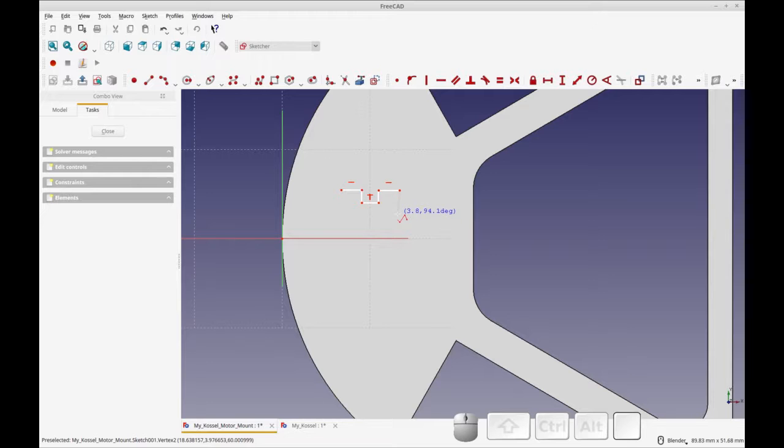So I'm going to go through and do all four sides like this, and just make sure you get that constraint on each one. And then after we've created this shape, there's three sets of equality constraints we'll be doing. And what you want to make sure is you don't get a constraint with that axis. That would make this a lot harder. Oops, so see that one, I missed the constraint, so we'll have to add that back later. We'll do that right after we finish. And I think I missed it on that one too.